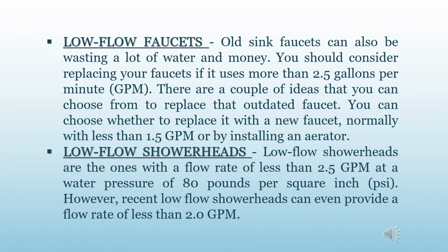Low flow faucets. Old sink faucets can also be wasting a lot of water and money. You should consider replacing your faucets if they use more than 2.5 gallons per minute. There are a couple of ideas that you can choose from to replace that outdated faucet. You can choose whether to replace it with a new faucet, normally with less than 1.5 gallons per minute, or